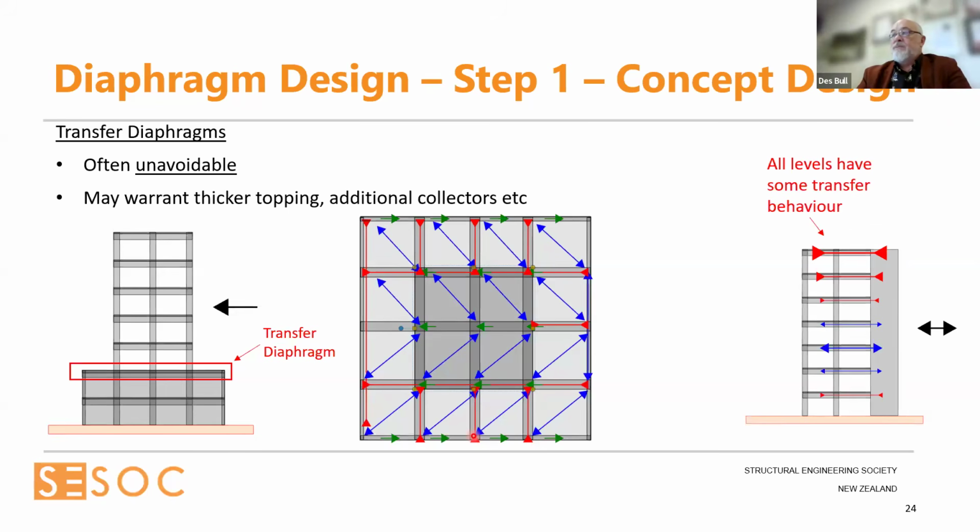The other thing to notice, just by the nature of buildings: in the textbooks, everyone says, "Oh, that is a transfer diaphragm." To some degree, all diaphragms have a sense of transfer to varying degrees. Some of them get absolutely hammered, but as soon as you start having this incompatibility of deformation, all diaphragms have some degree of transfer, and that's why we model these buildings in 3D to get all these actions out.